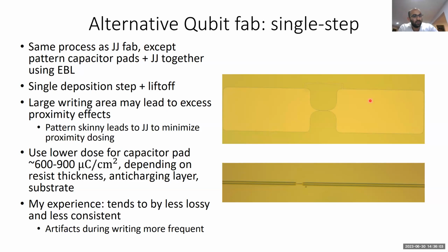One of the things that I've seen that are particularly annoying has to deal with the junction properties themselves. ESD, for example, is one thing that can really be a pain, especially after you spend a whole week fabricating a device and you find that it suddenly just shorts or blows up right at the very last step due to ESD. So I would say that's definitely a challenge.